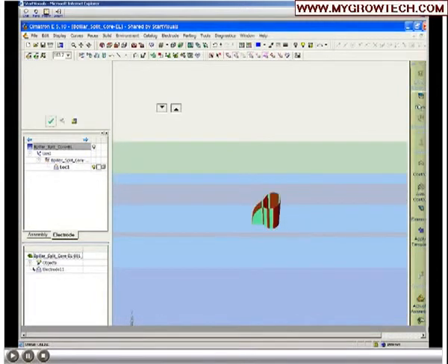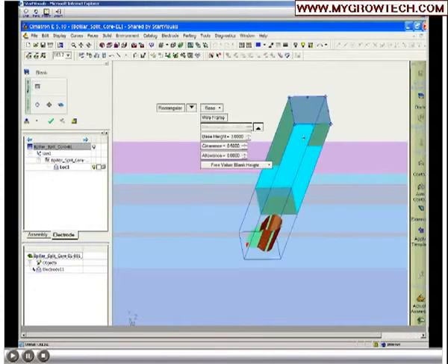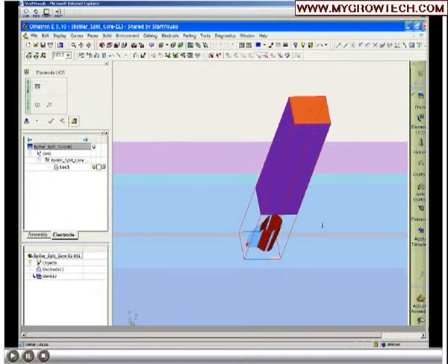Showing just that area on the screen, we can see what we're working with. We'll pull up the blank. See, these values have already been pulled from our preferences, so those are the overall values to begin with, but you can easily change them on the fly. The display updates to show you the results of the change as you're creating it. That looks good. We'll go ahead and work with that. Now we're going to tell the system where we want to pick the electrode up for our zero location. It can be on the back, on the clearance plane, on the burn tip, any of the four corners of those locations, or a point that you yourself would like to determine to be the pickup point.